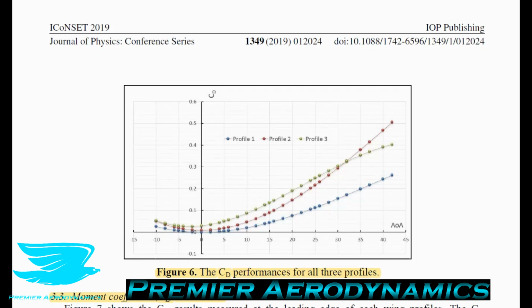By comparing the minimum drag coefficient, we can see that profile 1, which is the thinnest one, or the least cambered, has produced the lowest drag coefficient among the wing profiles, with a minimum drag coefficient of 0.000027. Now, this value I'm not too sure about. The reason why is because that's just really low for an airfoil. I mean, I don't even know any airfoil which is below 0.0001, let alone 0.000027. So I think maybe that needs to be checked.